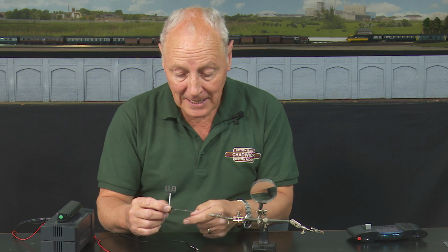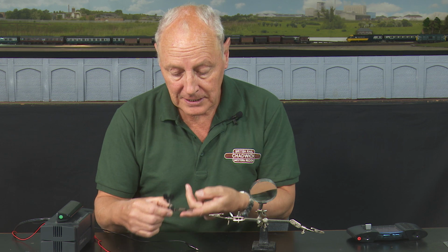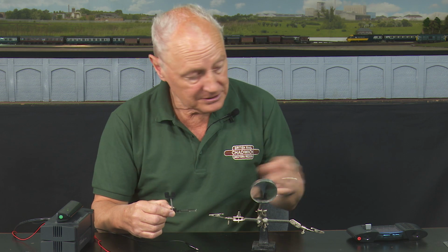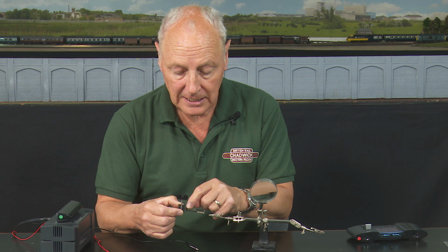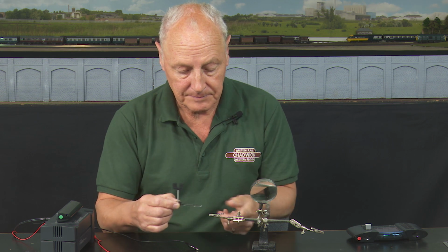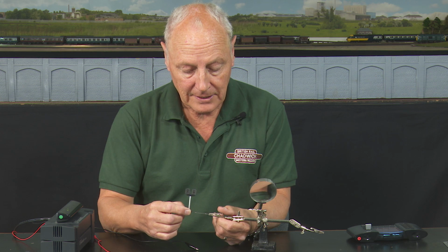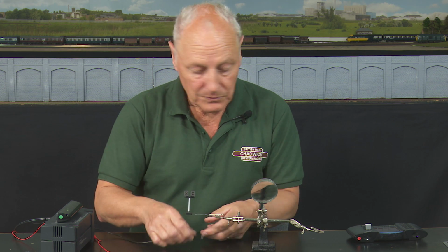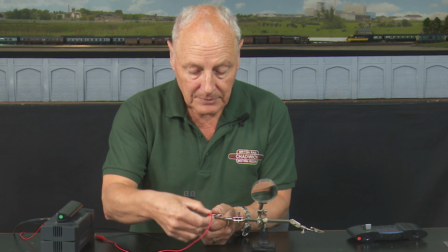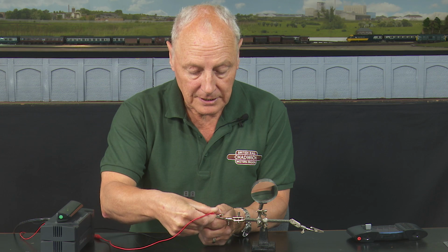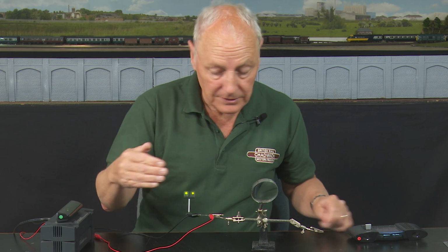There we go. And as you can see, there are these 2 prongs, and these 2 prongs are supposed to fit into Bachmann or Hornby track. But it says in the instructions, simply cut them off and you solder your DCC feeds into these 2 small contacts. Easy. Instead of doing that for this operation, what I'm going to do is just get my good old trusty Bachmann Dynamis, and then hopefully those lights will come on, and show you how they work.